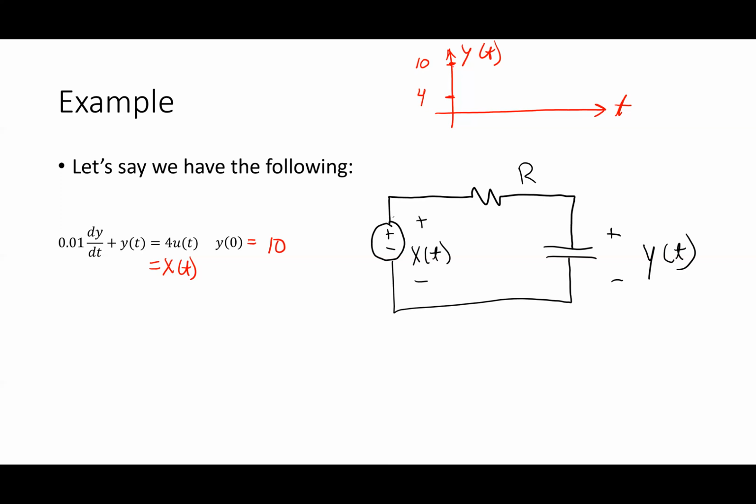At the end of the day, what you need to be able to understand intuitively is, if I get a first order circuit, I should know what the output's going to look like. You don't usually care all that much about the details of it, but you should be able to figure out what it's going to look like intuitively. It's going to be an exponential, and you should know where it starts and where it ends. And at what point does it level off here? Well, it levels off at 4, and at about 5 or 6 tau is where it's flattened off, right? That's how much time it takes for it to reach 4. Okay. So I know what that looks like. So I want that picture in my head because that's what I want this graph to look like, probably.